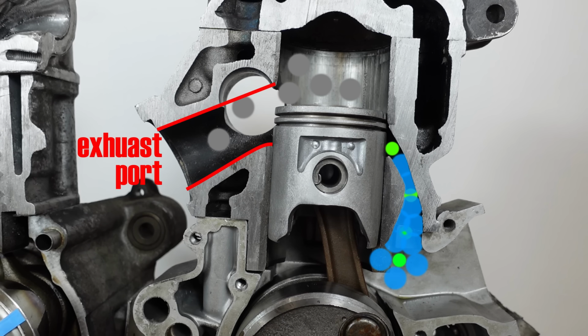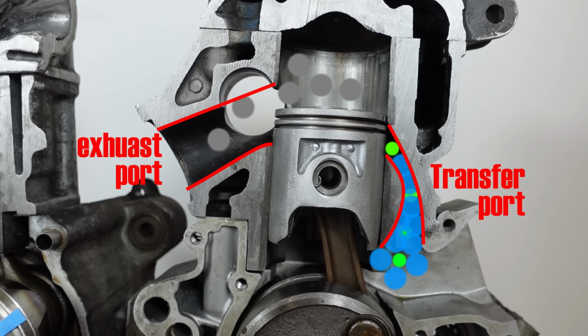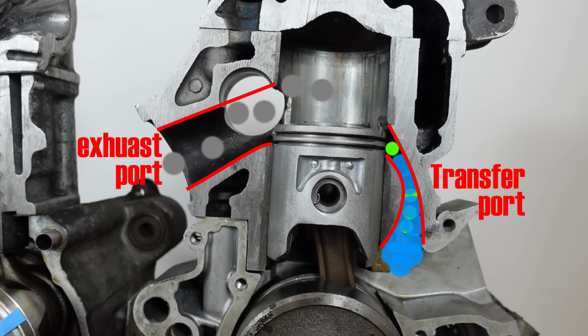And at the same time, the downward motion of the piston is also compressing the air-fuel mixture below it and pushes it into the transfer port, which is still blocked off by the piston skirt. As the piston goes down some more, it starts to open up the transfer ports.